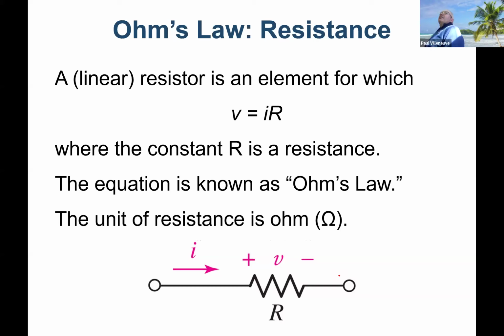Ohm's law. This is for linear applications, and this whole semester, and almost all of your college career, is going to assume things are linear, because if they're nonlinear, it makes things way more complicated. So we'll assume that the resistance is a linear element, meaning whatever voltage drop you see, whatever current through there, that resistance value is fixed. So V equals IR is Ohm's law. We'll modify that to V equals I times Z. Or we'll even do things in Laplace, where we'll include variables like S, the S operator.